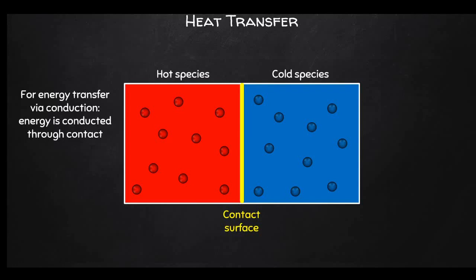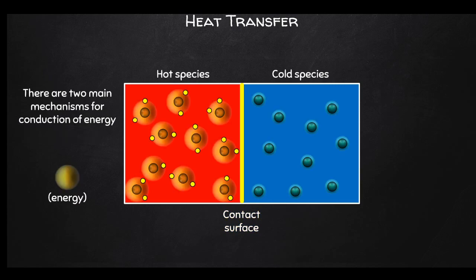Remember that each atom within these two control volumes has a certain amount of energy associated with it. Matter A, of course, has a higher energy than matter B. Now, how does heat conduction take place between matter A and matter B? It does so by two mechanisms. Firstly, heat may be conducted by delocalized electrons that are able to move around more freely within the matrix in question.